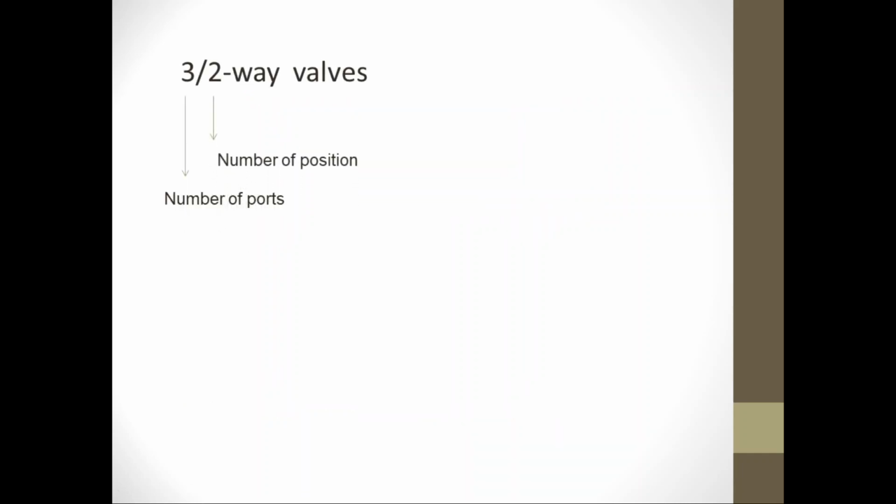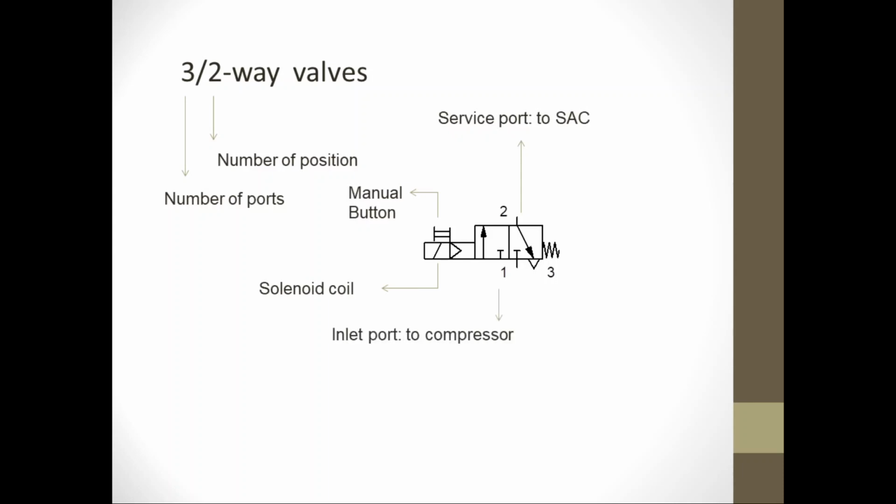So you have there the 3/2-way valve. 3 stands for the number of ports: the inlet port, the service port, and the exhaust port, so there are actually three. 2 stands for the number of positions, so either fully extended or fully retracted position.